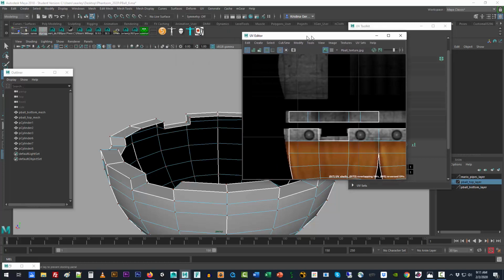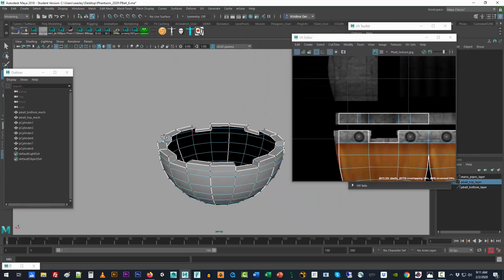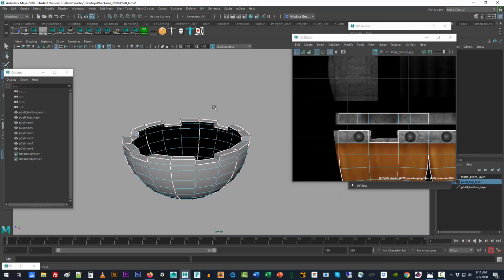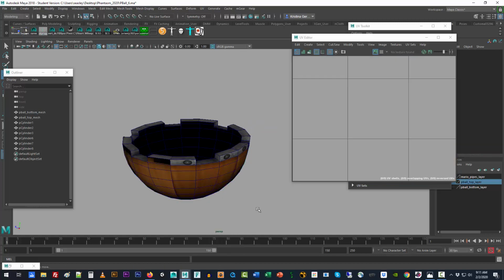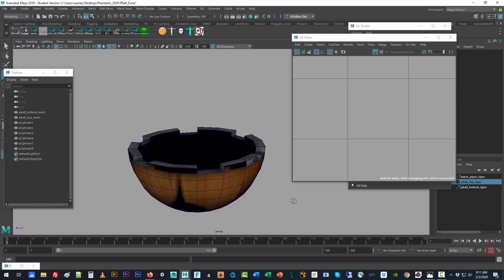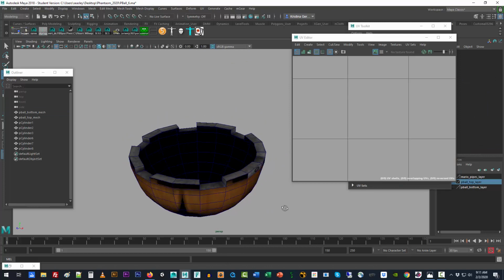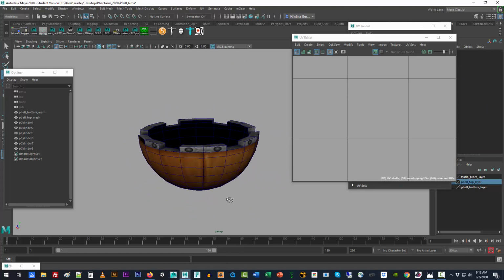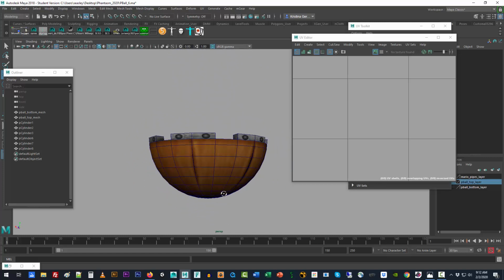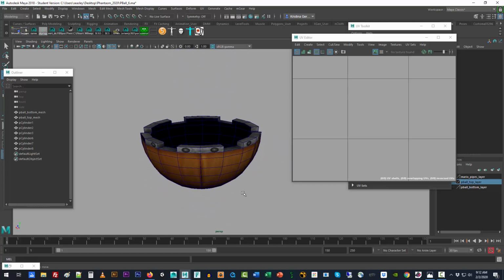So what you can do here, just with a little bit of work we've done, is give yourself a bit of gratification by going in here to the 3D modeling window and pressing 6, and things are starting to line up. You especially see the effect if you go into object mode and click off the object. That's not looking half bad. It's not perfect, of course. We haven't aligned everything, but there should be some section that looks pretty cool. At least it's beginning to, which is fine.